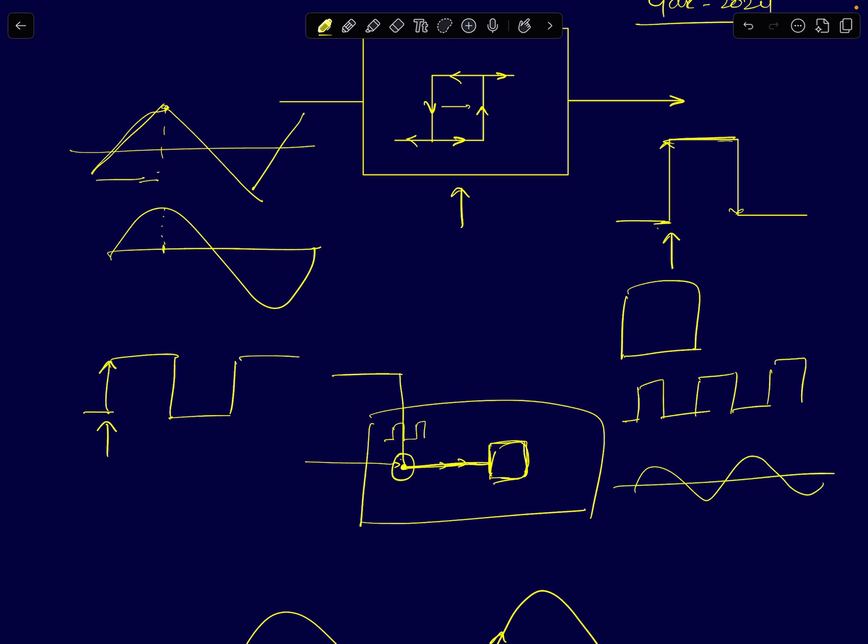So when the signal reaches the chip, when it enters the chip, the waveform will look like a sinusoid, or it can actually even look like a ramp waveform. If you think about it, a ramp signal and a sinusoidal signal are not very different. I mean, there are obvious differences, but if you observe a ramp signal or a sinusoid near the zero crossings, they both will look very similar.